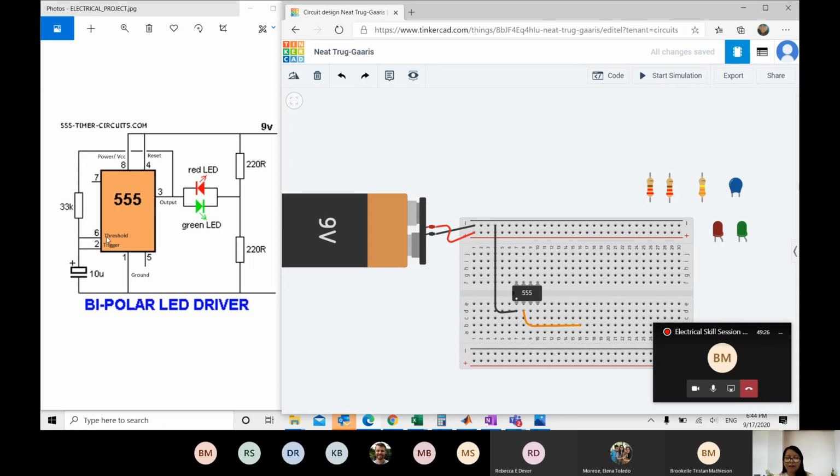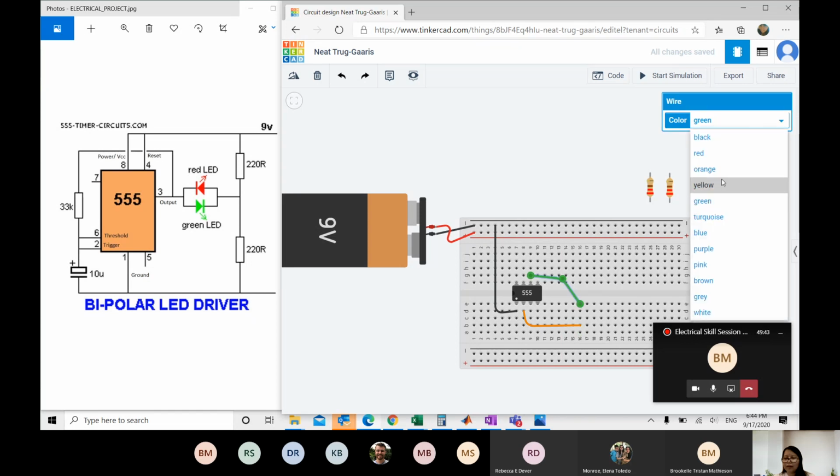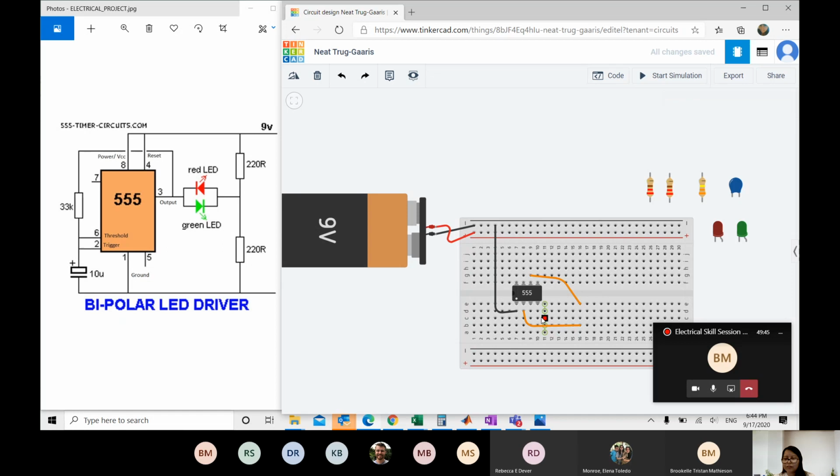We will find where it says threshold. So threshold, this discharge is not here, threshold is here. So you will click on here and we'll drag again. Let's make this a little bit nice. And we will do that. And I will color code orange again. So we know that all of these are coming to this portion. Now, we will need to connect to the same node a capacitor. What is our capacitor? Is this blue one here. So we can just connect it here.